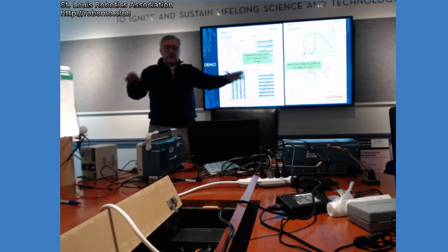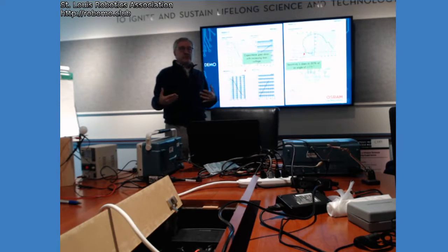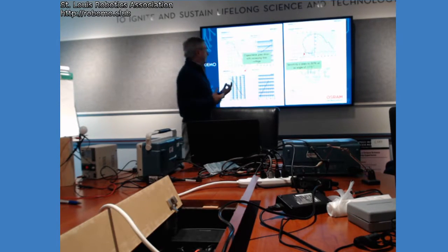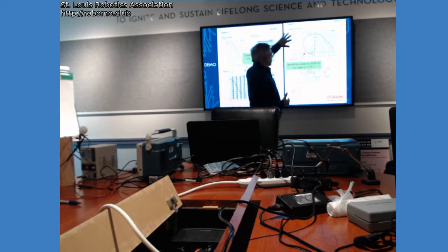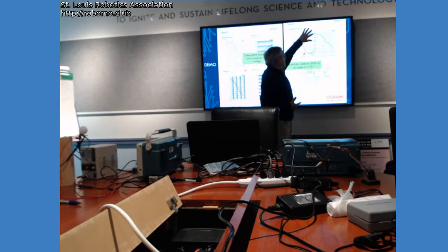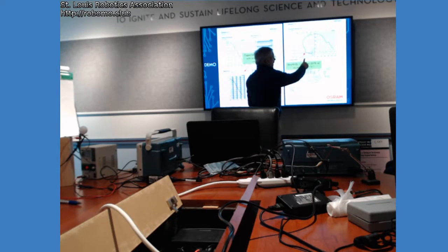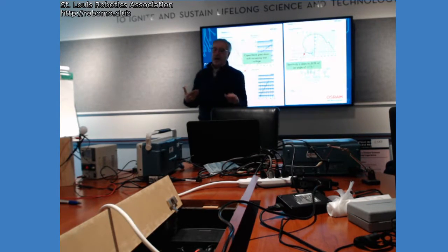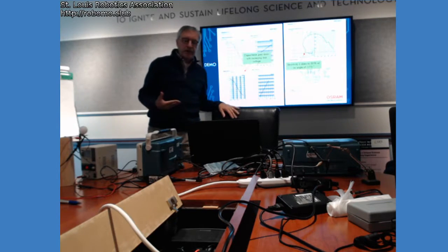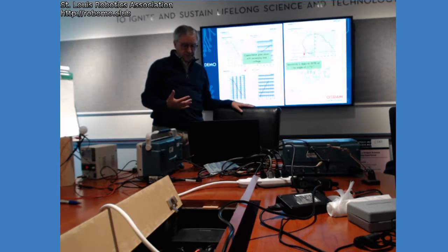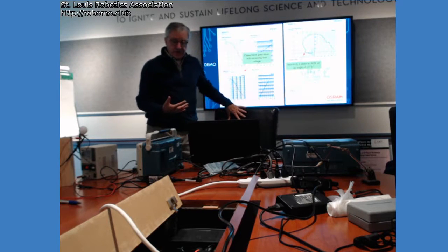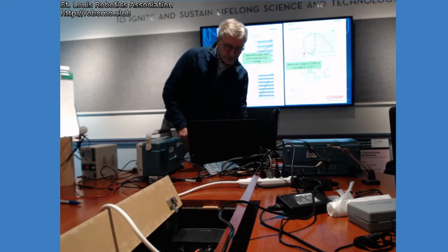It gradually falls off. The same is true for a detector, a photodiode in this case. You've got maximum sensitivity at 0 degrees when the light is coming right on, and by 75 degrees it's down to about half the sensitivity. So that's it as far as the presentation.